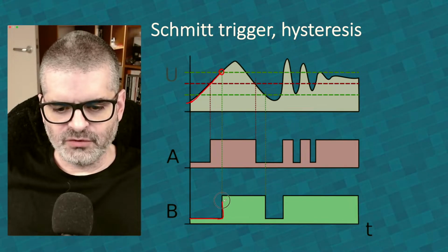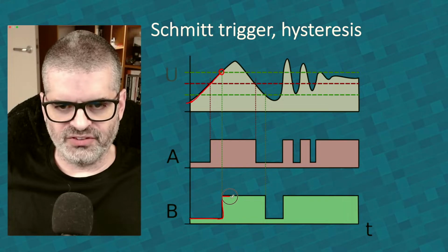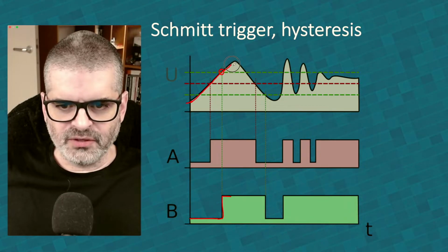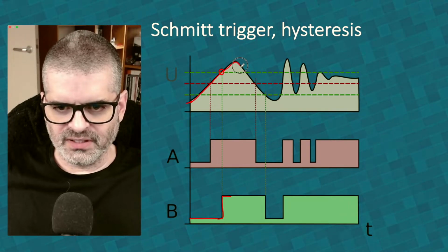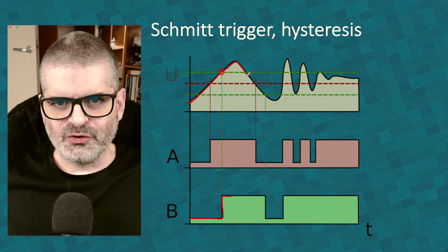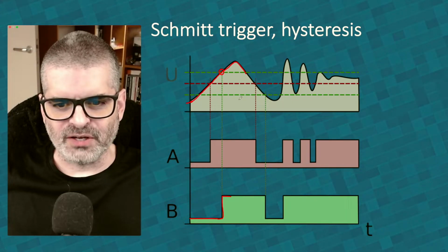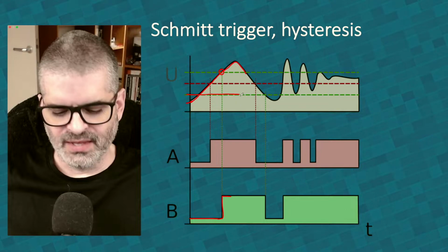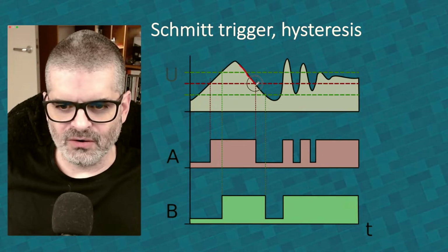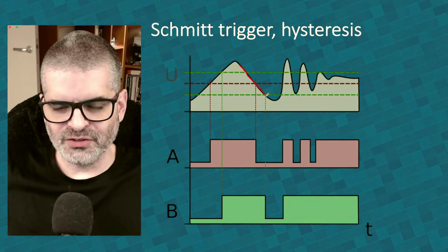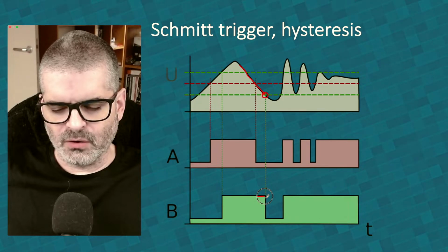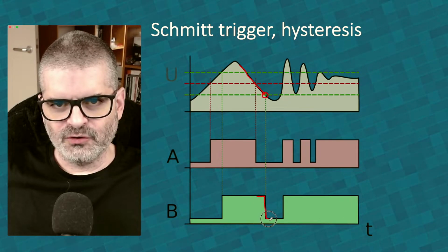Only then is it recognized by the chip, which sees this as an input, as a high signal. Now it continues to be high, continues to grow, and then goes low, and then it crosses that threshold. But now the threshold to go from high to low is another threshold. It's this one here. So what will happen is that the signal has to keep going low until it crosses the lower threshold. Only then will it go from high to low.